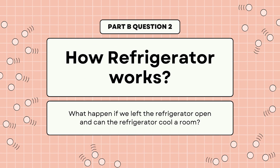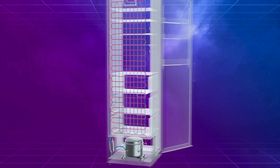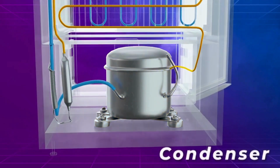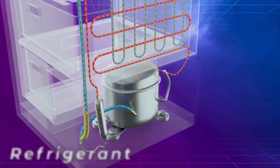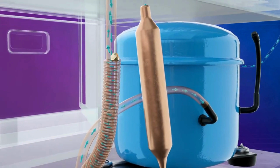Now, we are going to look at how a refrigerator works. A refrigerator uses a refrigeration cycle to keep things cool. It has a compressor that circulates a refrigerant through condenser coils, where heat is released into the kitchen, and evaporator coils inside the fridge, where the refrigerant absorbs heat, cooling the interior.